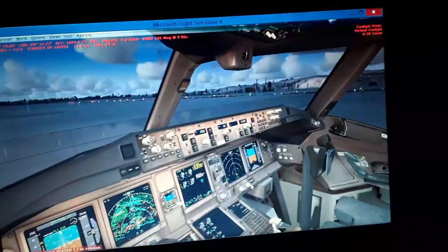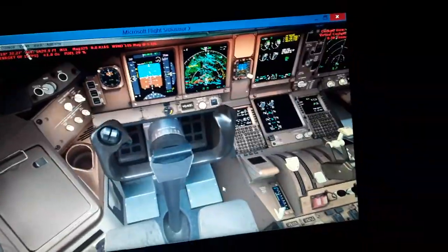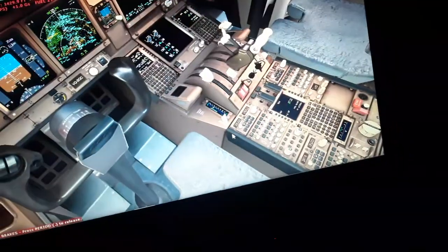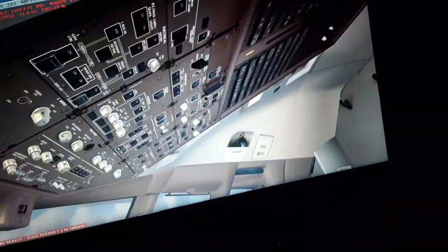You can see the cockpit of the Boeing 777 here. I'm showing you the yoke, the tiller, the rudder pedals, these flight control surfaces. Maybe I'm gonna show you the engines first, what they do. So maybe I'm gonna show you the thrust levers. I use the thrust levers to adjust the thrust of the aircraft as we move on the runway for takeoff, after starting the engines, or as we fly, to produce enough airspeed to produce aerodynamic lift to fly the aircraft.